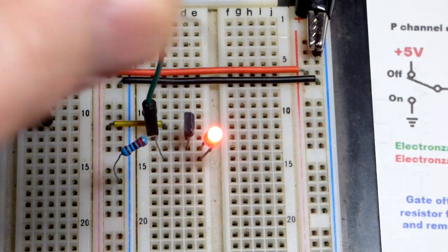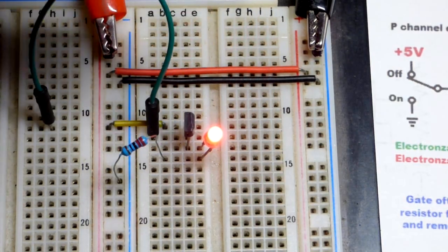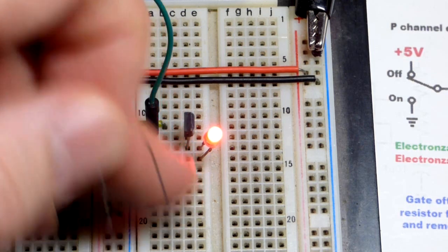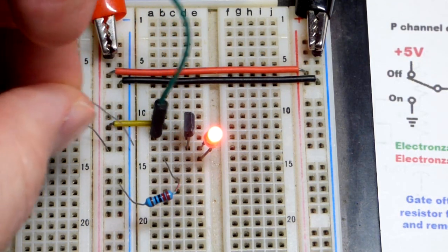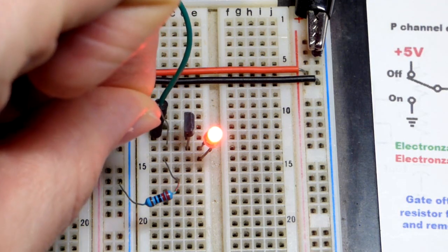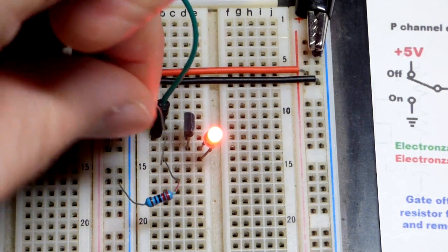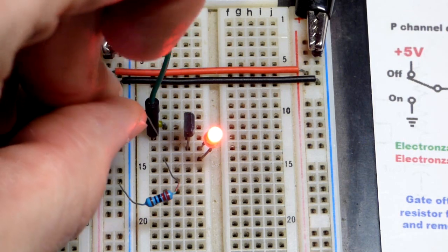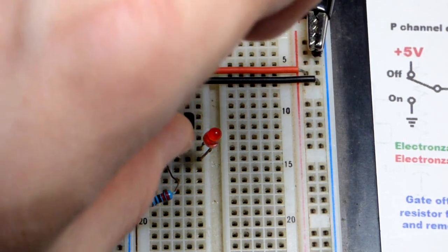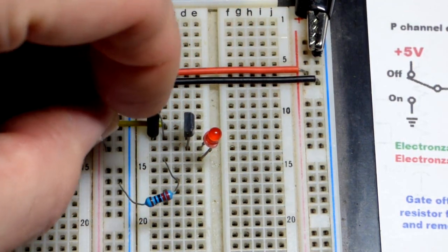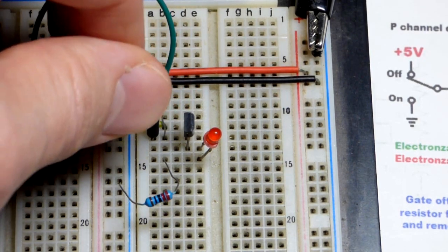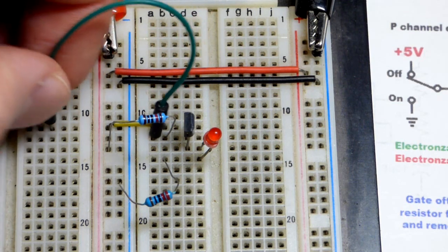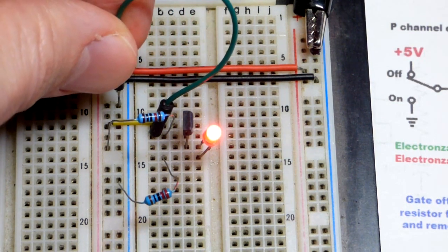So here's a 10,000 ohm resistor. If we want this to be off when we don't have a definite connection, then we can take the 10K resistor and put it to the positive supply right there, and then the gate. And oops, I went to the drain down there. All right, there we go. So yeah, now it's off. I don't think that plugged in great. Okay, it's off. Now we can get it on by putting the jumper to the negative supply.